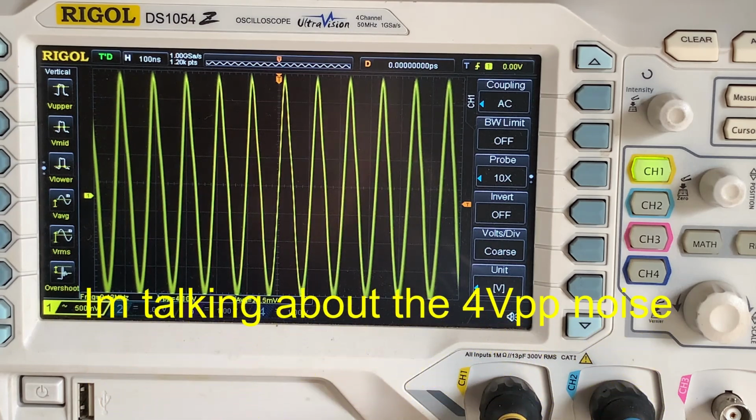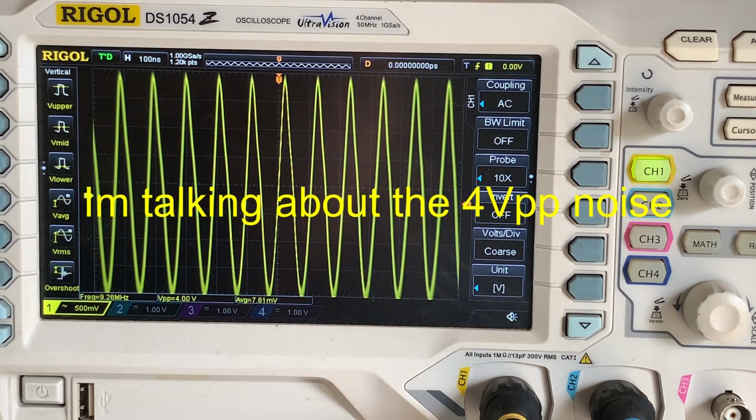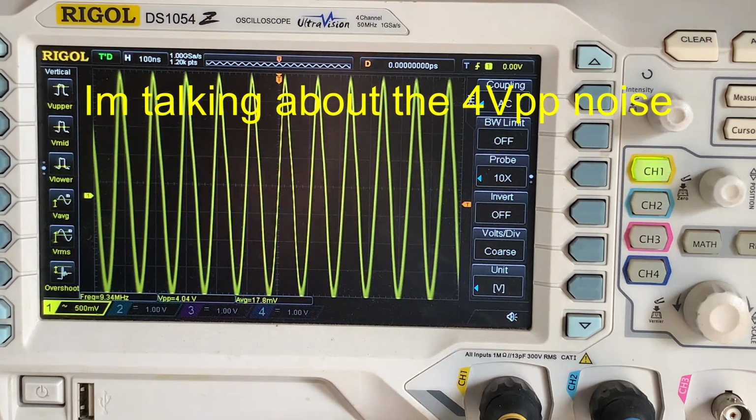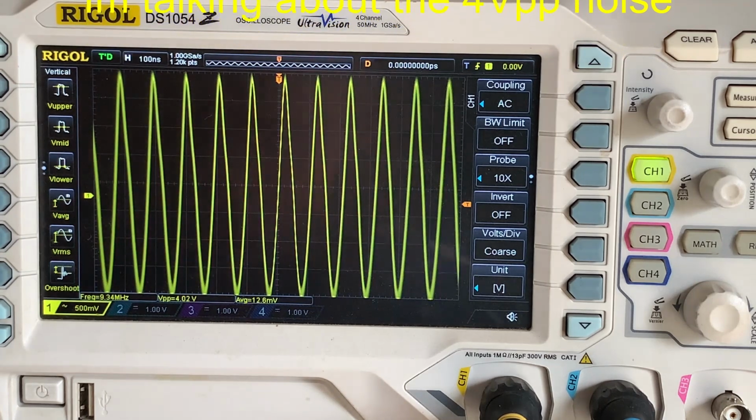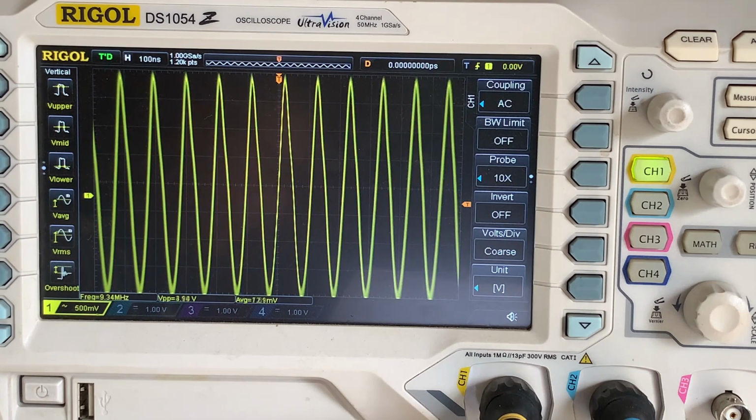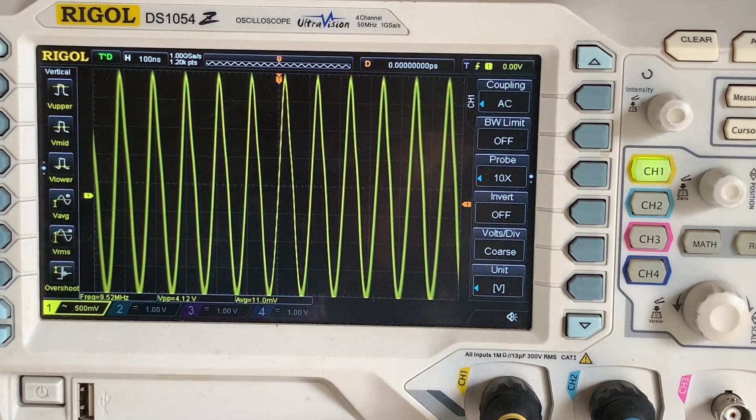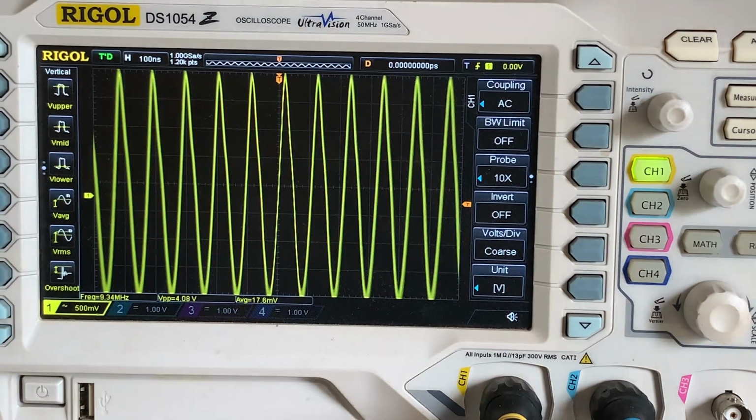That 21 millivolts, we really don't want it to be able to go and falsely trigger our gate, even though on the gate we did put in a 100 nanofarad capacitor. So what I'm going to do, I'm going to put a little 100 nanofarad across the rail that I showed you early on, and watch what happens to that signal.